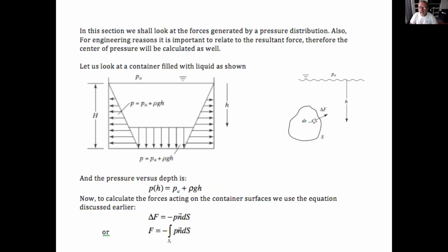And this is really the main part of that particular chapter. Before, we did how the pressure is changing with the depth in the liquid, the rho g h formula, you know this from high school. Then we invented a case when the fluid is accelerating, but in a sense it's the same as the gravitational force. It was really just to show how you place the body forces in the equations. So very, very simple. Now this part is actually far more important for engineering because now we're going to find out how a force is generated by the pressure term.